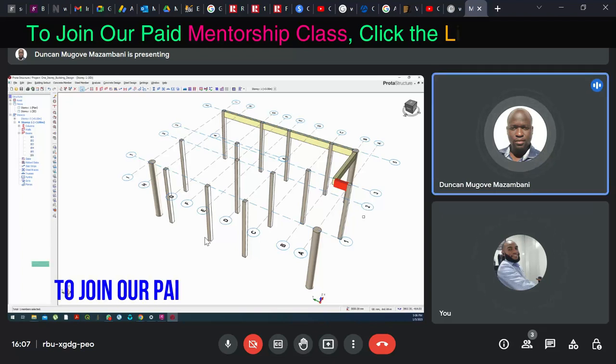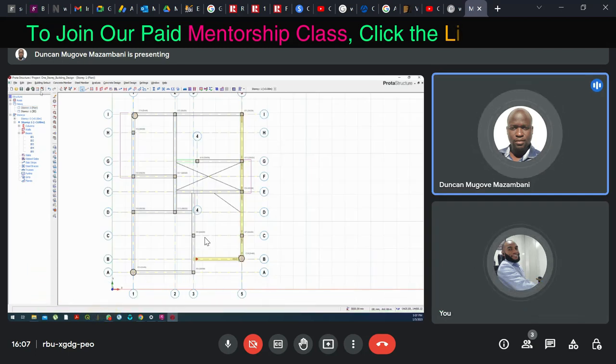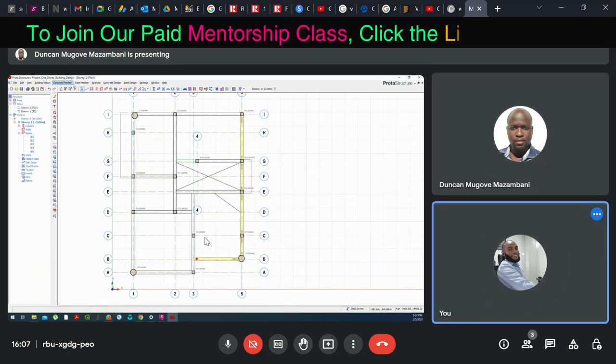Okay, so I need to delete this one. Now go back. Let me go back to my plan. With that, you have to first delete this other beam before you can put that one. Delete that one first and then start with the one that will carry it. So put the beam first. Else, if you don't do that, it will be showing you questions: do you want it to be a secondary beam or that? So just to avoid that, insert this one first.